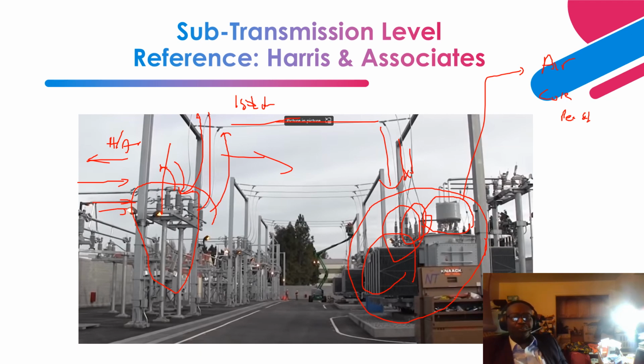Sometimes when substations are being designed and built, as part of the planning stage, system studies are performed: load flow, short circuit analysis studies, protective relay coordination studies.